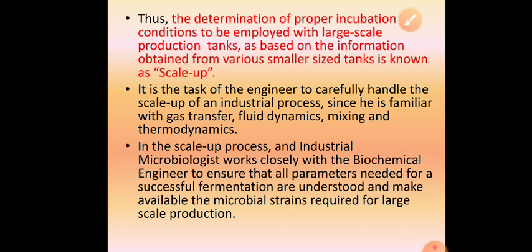So there are chances that microorganisms in a large tank may come across anaerobic conditions. Thus, the determination of proper incubation conditions to be employed in a large scale production tank, based on the information obtained from various small size tanks, is known as scale up.